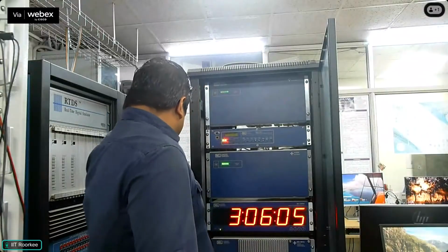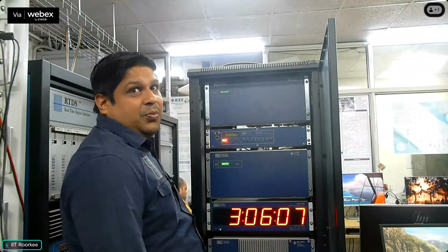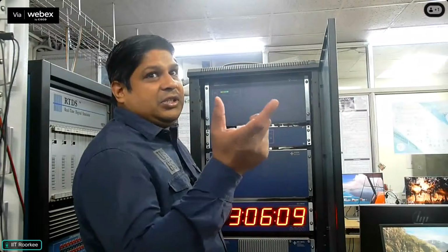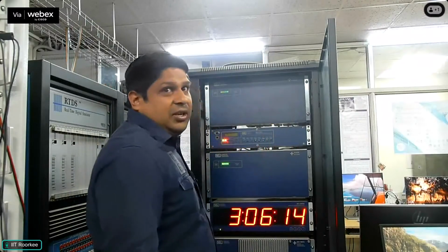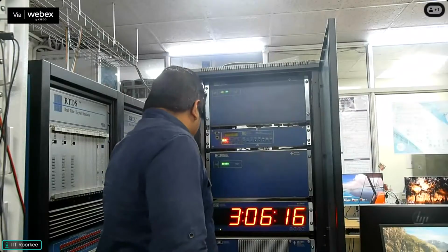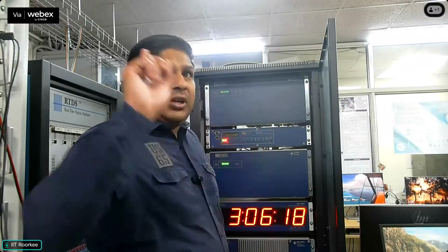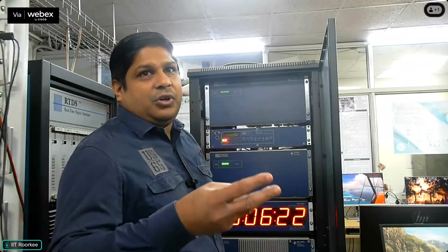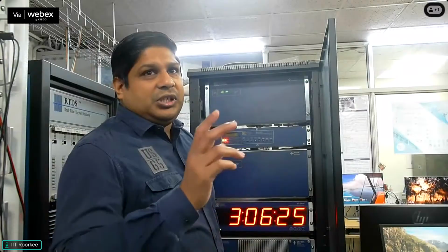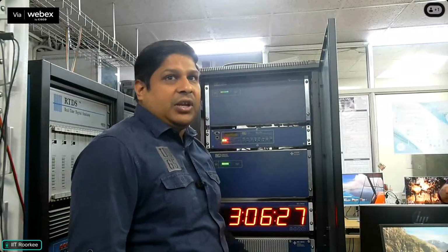Okay. These are the DI, digital input. So from relay, if we give digital signals into the RTDS, we use these digital in channels. We have 24, something like that. But AO, it has only 12 channels. We only use 6, 3 for 3 voltages and 3 currents. So 6 we are giving it to here, and then we are amplifying it.